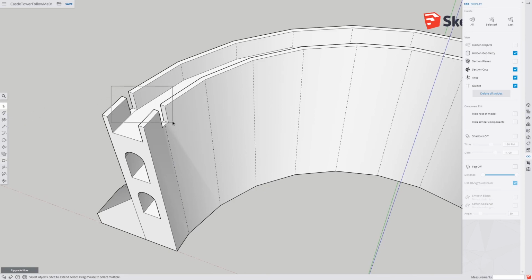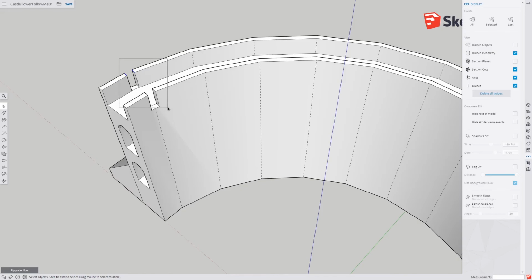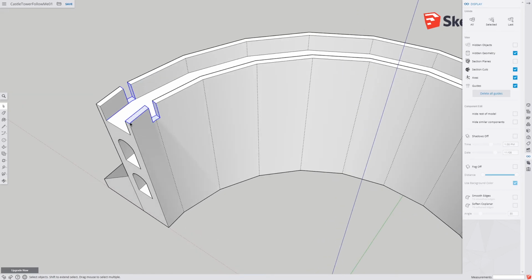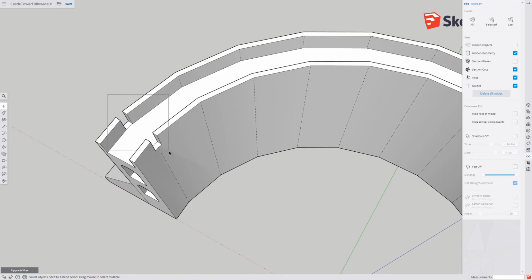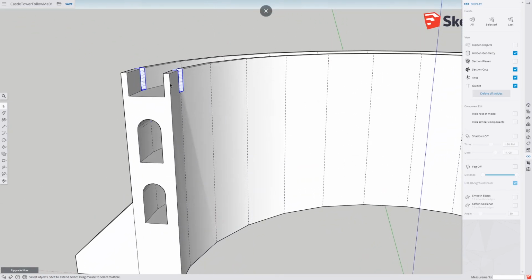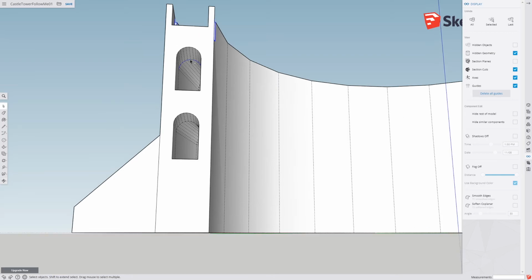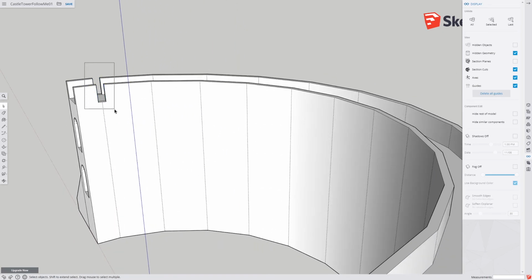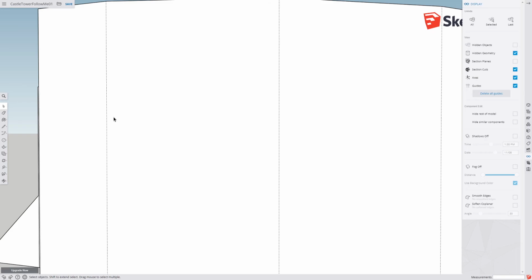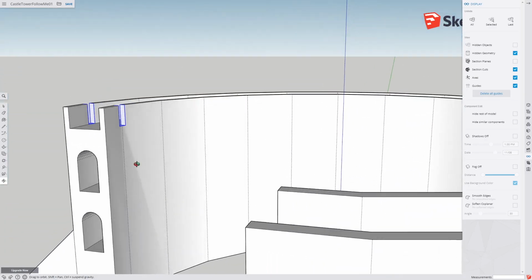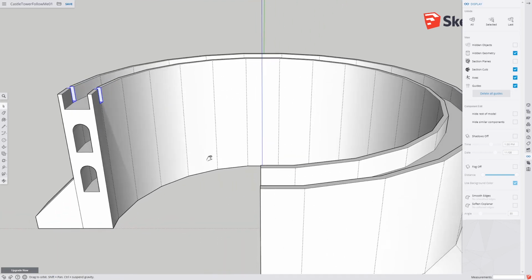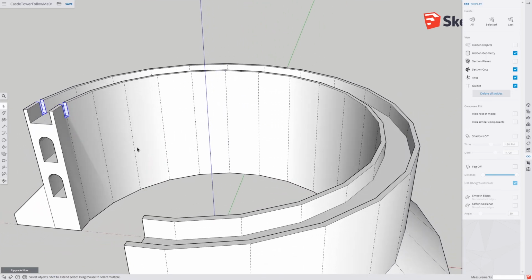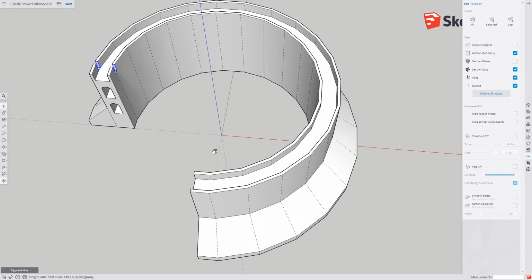Late in the day, I'm not thinking. Move it to where I'm going to get a good circle. So I don't want that because I'll end up with this face and that too. I want to limit it. I'll get rid of that with the shift. Okay, so I use shift to unselect anything I don't want. Oh, there's one in here, so I'm going to shift. Let's get in a better spot. There. No, don't have any unnecessary lines. It wouldn't affect too much, but it would make my drawing and my life messy.